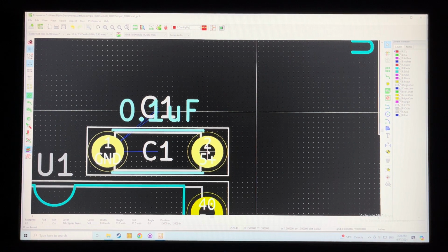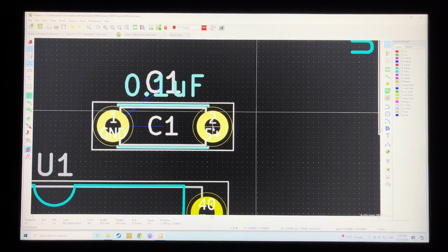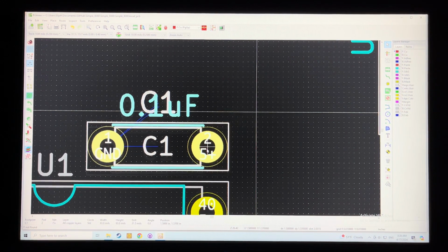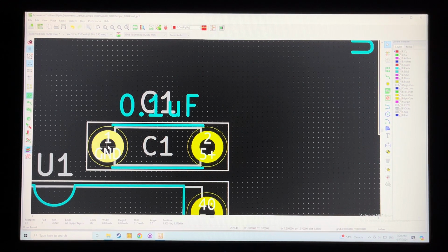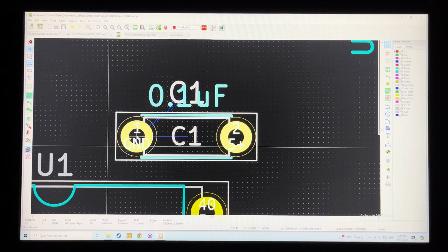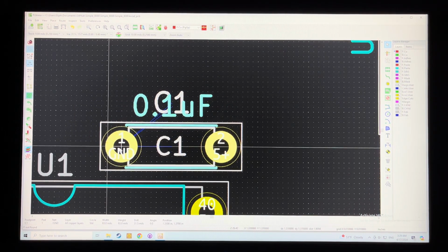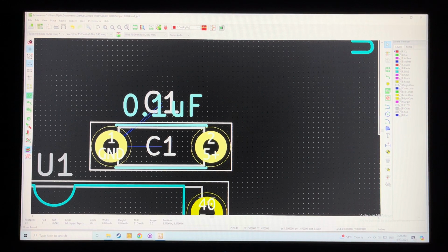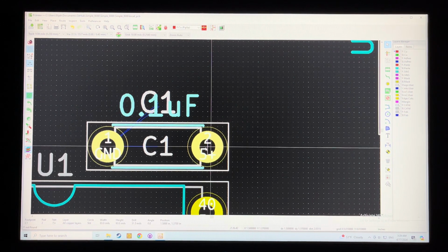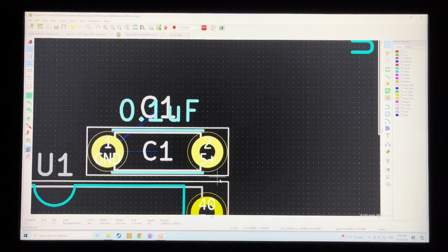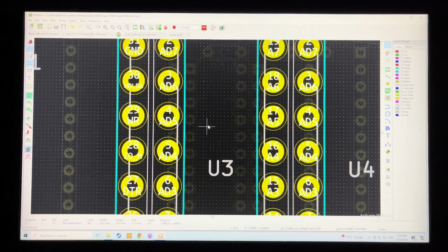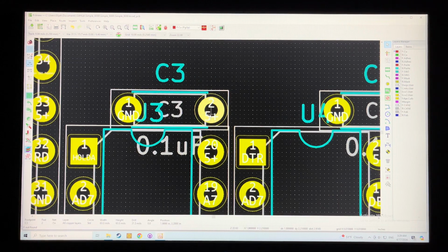In some of my projects this is spaced wider, but at 10 mils you've got these dots to help you line up. And these are not spaced evenly. So if you select the ground, it's going to align that to grid. And you can see the 5 is not lined up with the 40. I like to line that up. And then I'm going to make it so that I see one little row of dots at the bottom. And so then we'll do the same here.